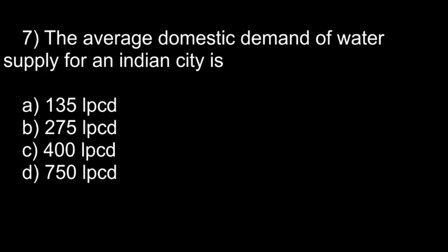For fire demand, commercial and institutional purpose, it is 20 LPCD, that is 5 to 10% of 270. Losses in waste and thefts is 55 LPCD. Such a large amount is waste as theft and wastage. So total per capita demand is 270.